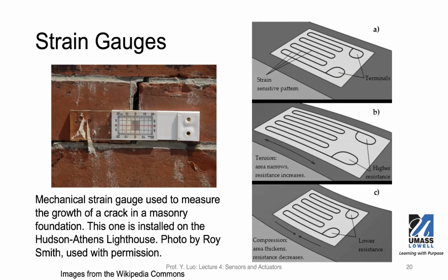The tension will cause the area between these sensitive patterns to change. As a result, that will change the circuit's resistance. So by measuring the resistance, you can understand how these surfaces change their shapes, change their formation.